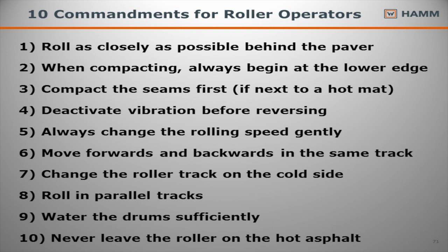It wastes time because now you're wasting time trying to get as close as possible. If you're at least a length of the roller away from the back of the paver, that's as close as you need to be. You don't need to be any closer than that. Absolutely. There's a lot of things that could happen.